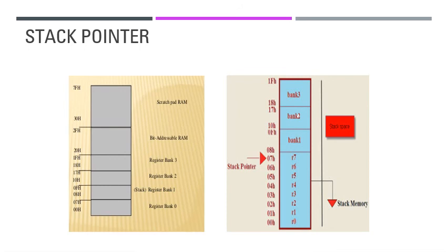The address of the stack is contained in the stack pointer register, which itself is present at location 81H. It is accessed by the basic move command, and data is written into or extracted from the stack with the help of push and pop commands. The stack pointer in 8051 is only 8-bit wide, which means that it can take the value 00 to FFH. When 8051 is powered up, the stack pointer contains the value 07H.